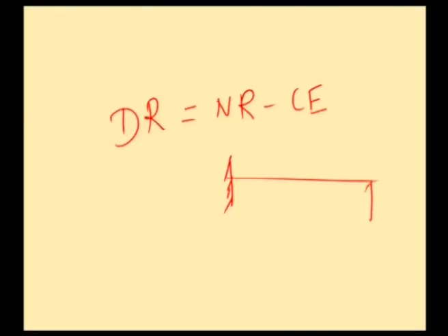If you have a propped cantilever, say this is A and this is B, say this is the reaction at B, we will have V A, H A and M A. So, 4 unknowns are there and we have 3 equations. Therefore, the propped cantilever is indeterminate to 1 degree. So, the degree of redundancy is 1.